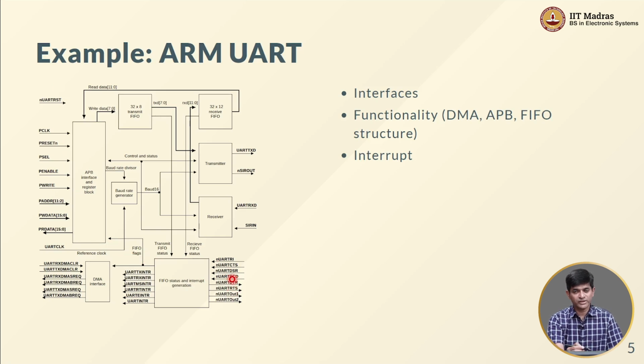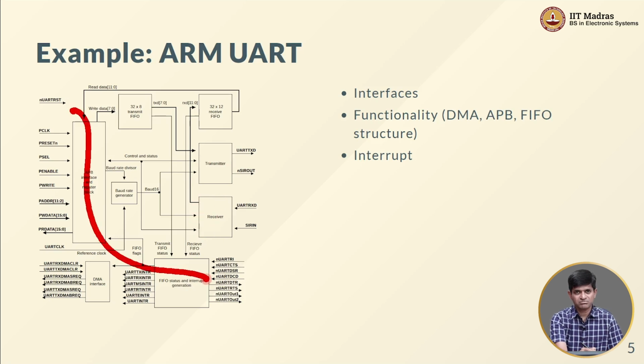Now, what do we do with this? In other words, if we read through this part and look carefully at this picture, we will understand the what. What is this device capable of, right? And the functional overview will describe a lot more in detail. For example, what kind of baud rates can be handled, what is the depth of the FIFO, and what is the implication of that in terms of how the data can be sent. Any information that you really need to know as far as the transmitter and receiver are concerned. For the most part, from the software point of view, you probably do not even need to know how these work, right. The rest of it is sort of a black box.